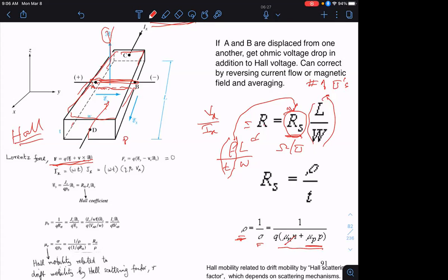How does it work? Well, you still measure the resistance by applying a voltage along the X direction, but then you also measure the resistance in the presence or absence of a magnetic field B in the Z direction. All right. Now, if I have a magnetic field, you may remember from your physics 303L class, the particles see a so-called Lorentz force, F, given by the charge of the particle.